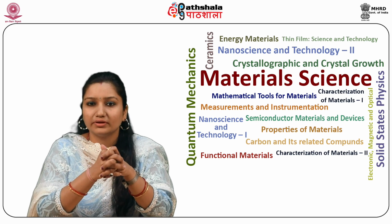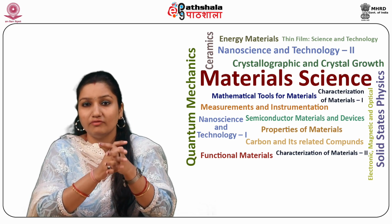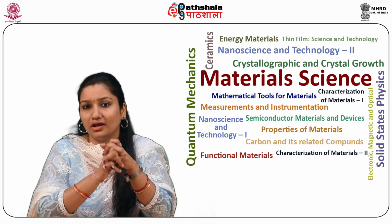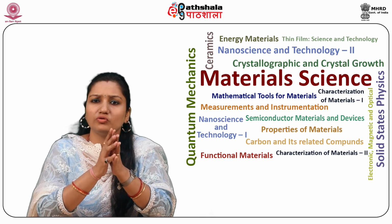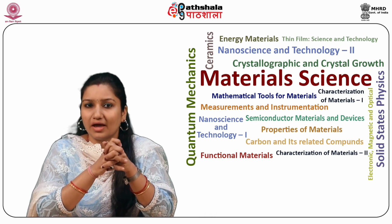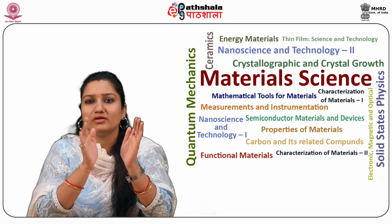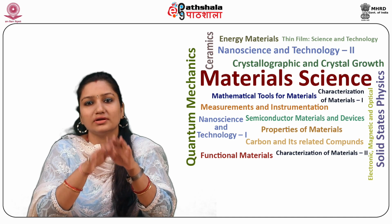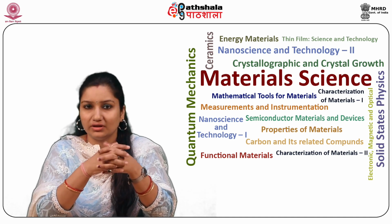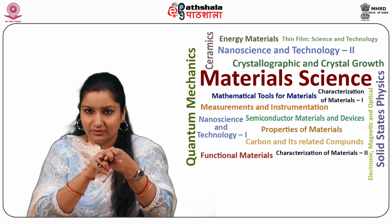MBE is performed in ultra-high vacuum, that is of the order of 10 to the power minus 11 torr. It is a very slow growth process, so very precise control over the major compositional variations and impurity incorporation can be achieved using this technique. Now there are two types of epitaxy.